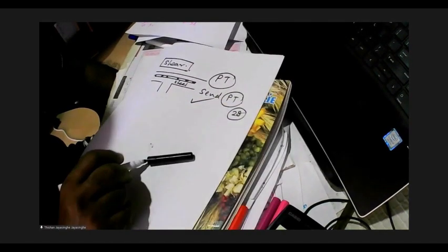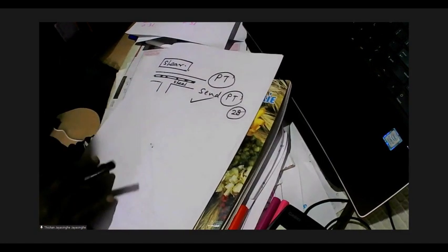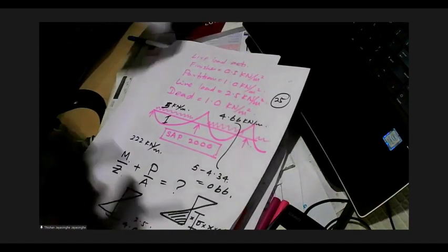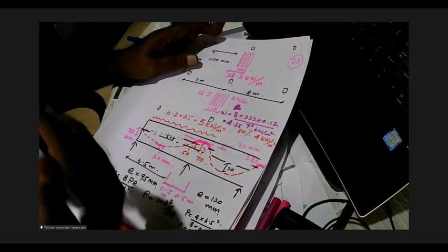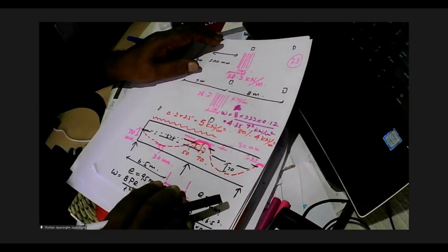So this is how you have to look at the flat slabs. So you can do reasonable calculations. They are not 100% accurate, but you can see the concept. And the concept is, you know, we try to convert it to a one-way system, and using load balancing, we try to see how much load we have balanced.